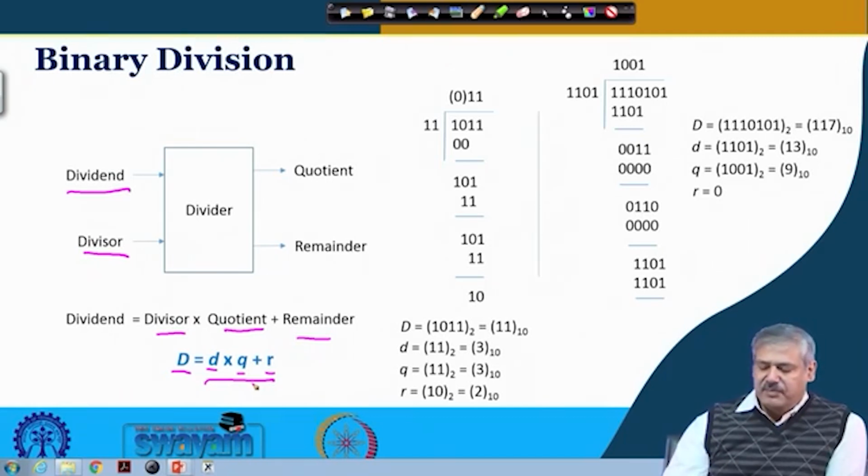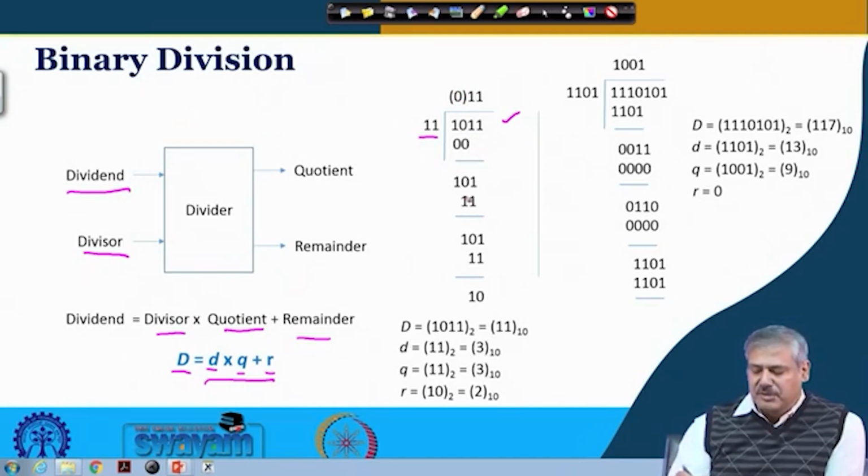So, if you take an example, say 1 0 1 1 is getting divided by 1 1, okay. First of all, this 1 0 is small, right. So, even if you multiply, you have to multiply it with a 0 only, leading 0 does not make any sense. So, this is 0 0, if you subtract you get 1 0 only, and then you take the next bit, okay.